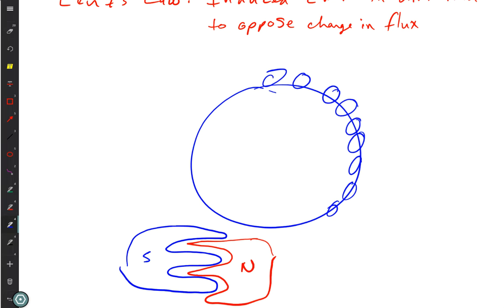And then you have the loops that are just above that. They're having the flux change rapidly, inducing an EMF in those little loops around the outside. This is both a more efficient generator and it's more robust because you don't have your loops rotating. Your loops are fixed and stationary, so they're not going to have as much stress on them as if they were the things rotating. And so it's more robust and it is more efficient. But what it won't do is it won't work as a starter motor. So that's what we have today in our cars is alternators.